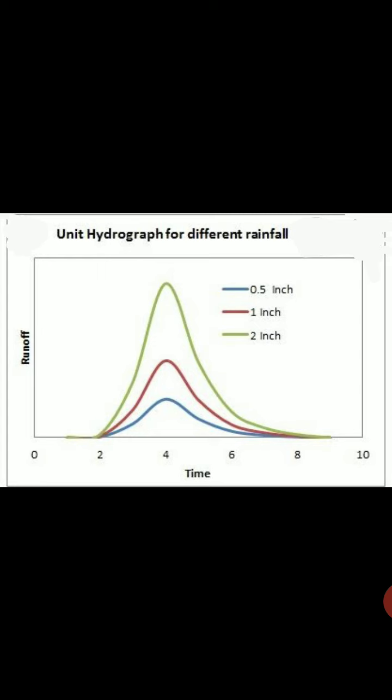Second point, the catchment should not have unusually large storages in terms of tanks, ponds, large flood bank storages, etc., which affect the linear relationship between storage and discharge. If the precipitation is decidedly non-uniform, unit hydrographs cannot be expected to give good results.